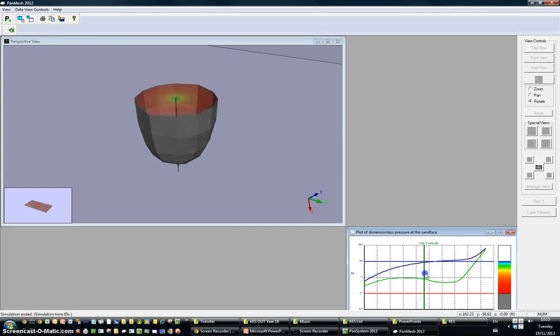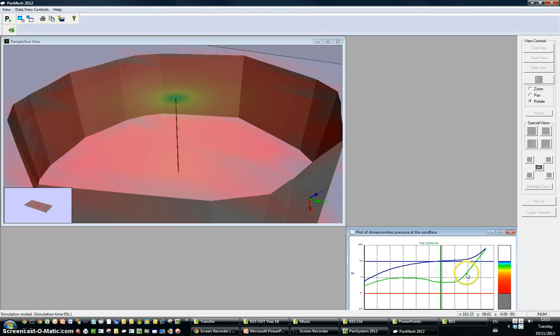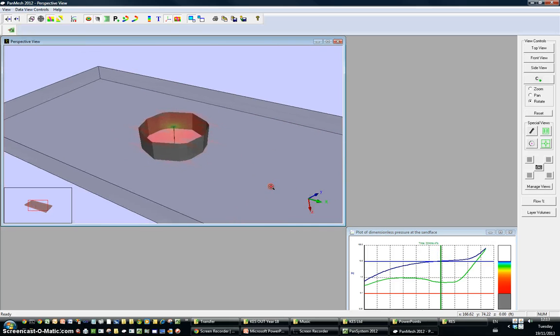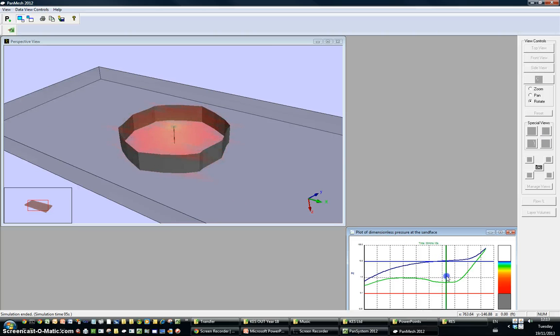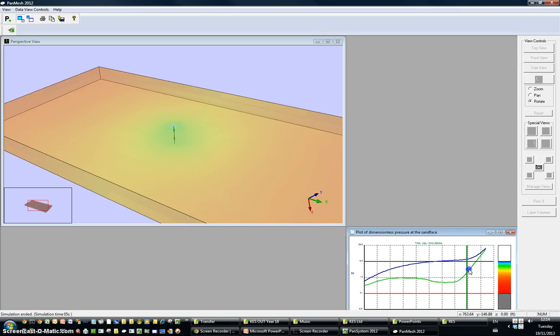And as you would expect, as you get out of the partial completion effect, you get into standard radial flow here, which you see by this horizontal section with a derivative value of 0.5 roughly. And if I zoom back out a little bit further, we see the radius of investigation move out and hit the boundary, and as it hits the boundaries we get the upturn here in the derivative, etc.